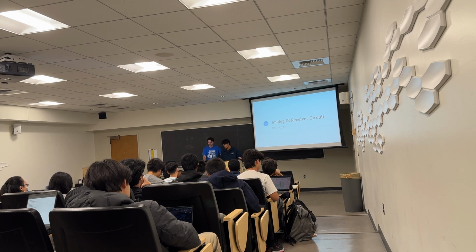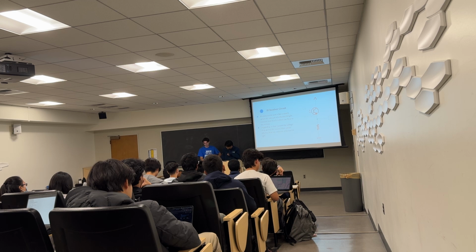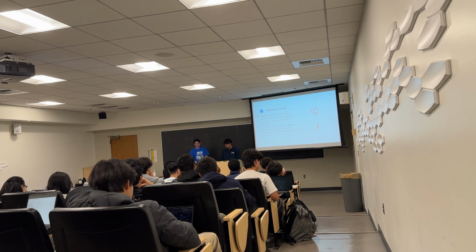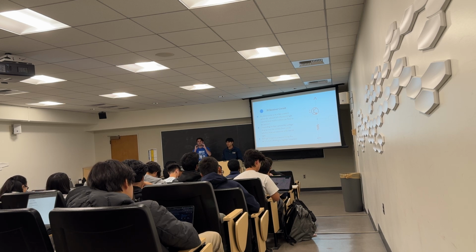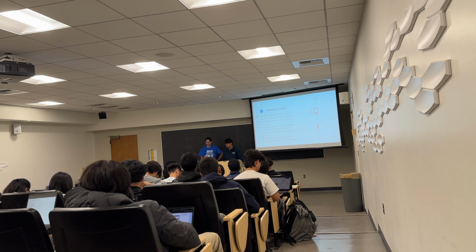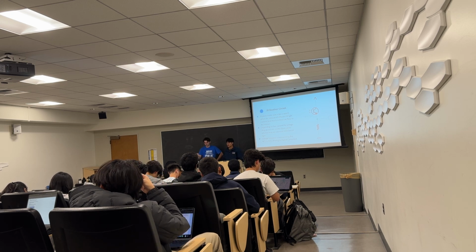All right, let's look at the IR receiver circuits. Okay, let's apply all of it. Our phototransistor, which is that Q1 thing, if you look at it closely, it's also a transistor, it's in the name. So it's going to act like a switch, but instead of applying a voltage to the base, the amount of IR light that it receives, or that's reflected off of an object, is going to control how much current can flow through the transistor and then also through the resistor.